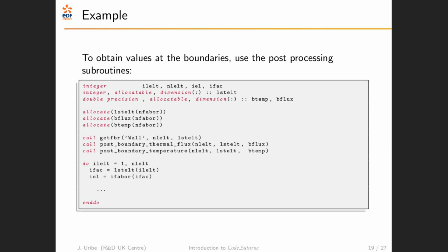It's also worth reminding that the periodic boundary conditions are actually not periodic conditions. They are not boundary conditions. The periodic boundary conditions are actually treated like ghost cells. You see that the same type of ghost cells you would have when you do parallel decomposition.